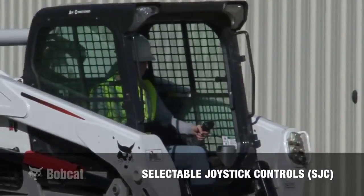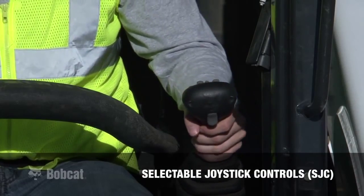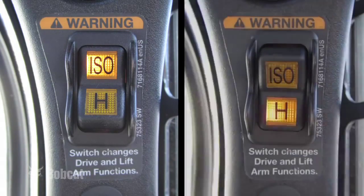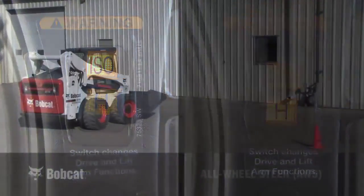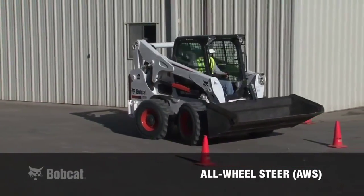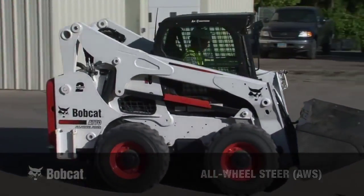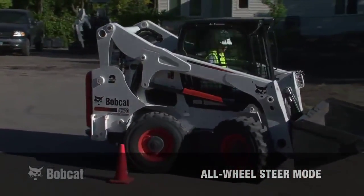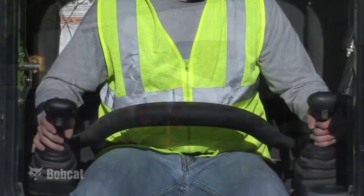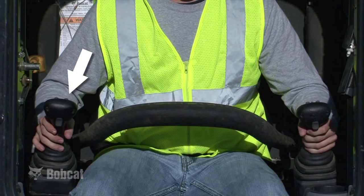Loaders equipped with selectable joystick controls, or SJC, provide joysticks to control drive, steering, lift and tilt functions. 2 control patterns are available, ISO and H. The Bobcat all-wheel steer, or AWS loaders, also provide joysticks to control drive, steering, lift and tilt functions. The operator can select between 2 different steering modes, the all-wheel steer and the skid steer mode. Regardless of the steering mode selected, the left joystick controls drive and steering functions, while the right joystick controls lift and tilt functions.